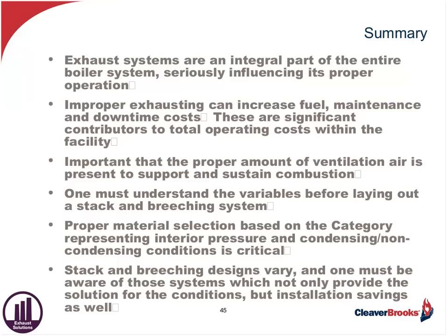Now, there are some boiler manufacturers that can, based on the boiler burner package, tolerate plus or minus a quarter inch, plus or minus a half inch, but that depends upon the manufacturer. So it'd be a good idea for the engineer who's involved in laying out that stack and breeching arrangement to understand what boiler is being connected to it. They should contact the manufacturer and ask under what conditions they can operate without adversely affecting combustion.